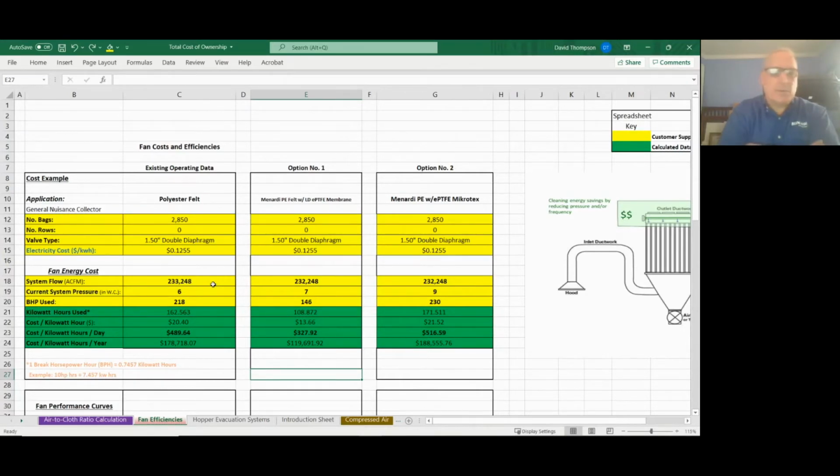So in order to make that more efficient, typically a Precoat is used. That Precoat reduces the air permeability, protects the surface of the material from dirt being embedded in it, and makes the bag last longer. But there's a cost for that.